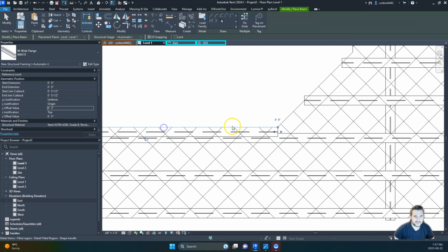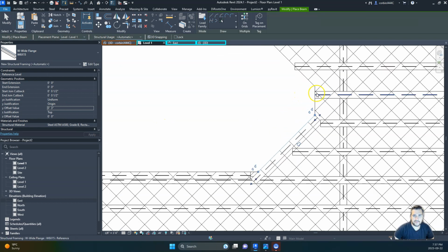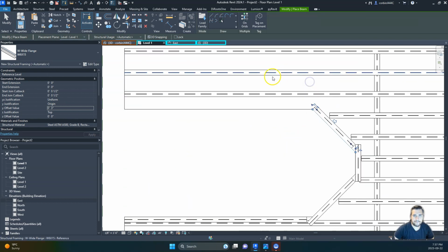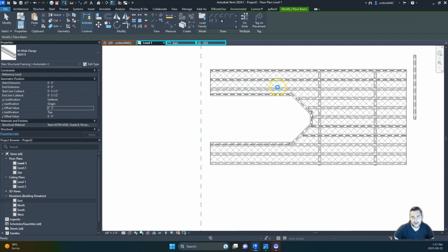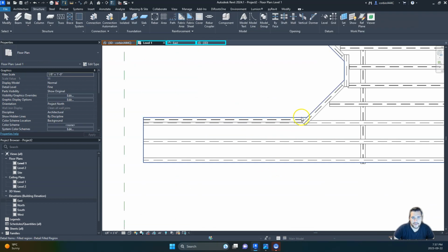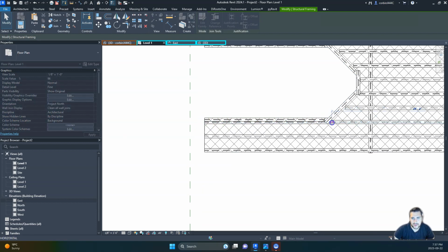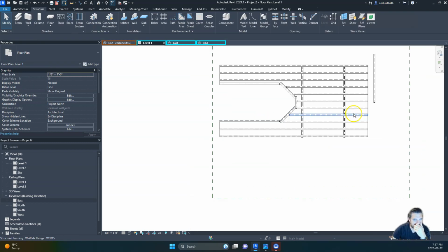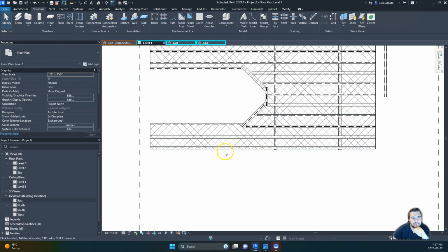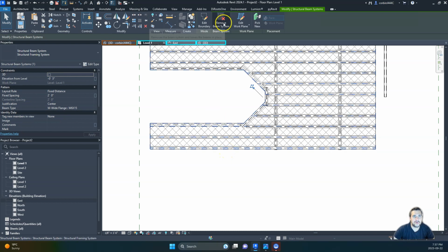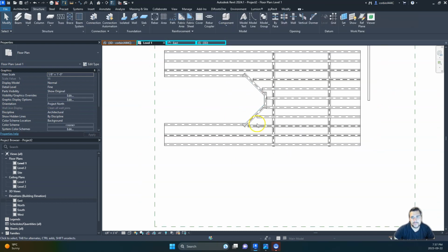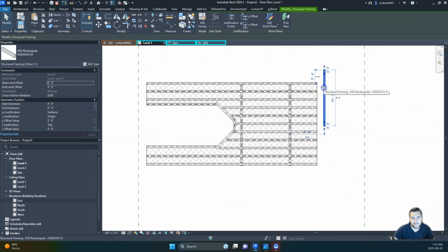And when we pick this, it's not offsetting. I'll fix that in a second. And so now we can just kind of go around that slip area. And this piece right here, we would want to unpin it, and we would just bring it back. Usually after I set up the beam system, we'll delete it, and just keep all the members. So you can tab over the beam system here. We can go to remove beam system, and we'll keep all the beams in place, but removes that system per se there. So that's generally how we set up the dock.